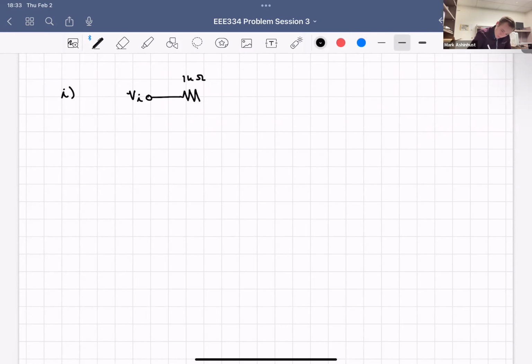And we have what I was talking about earlier. I was saying we didn't have 2 resistors. Now we do. So I'm going to toss another resistor here, and also a diode with our anode, cathode. Name that D1. And to ground, we have 1 kilo ohm. And then this goes out to V out. So this is what we have for I.